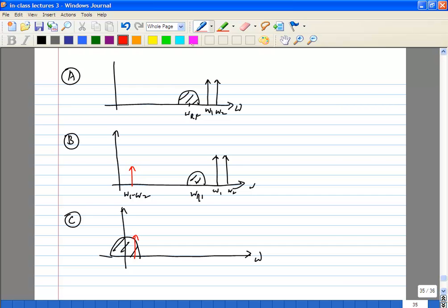So any even order distortion, especially a second order distortion, can corrupt your signal. What we are assuming here is, remember, normally this goes through the mixer and would get upconverted to some other frequency. But we are assuming that the mixer has some limited RF to IF feed through.